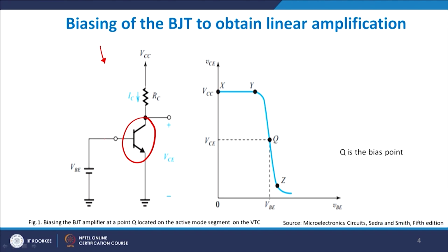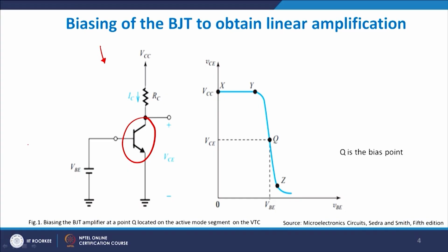Now the obvious question: how do you physically amplify? When you amplify any signal, how do you do that physically? First of all, you apply a DC bias onto the device which you are supposed to amplify. Once the DC bias is applied, you need to superimpose the small signal over the DC bias in order to sustain an output voltage variation. So I mark my DC level, and superimposed on that I have an AC cycle, which multiplied by the voltage gain AV gives me the output for any BJT.